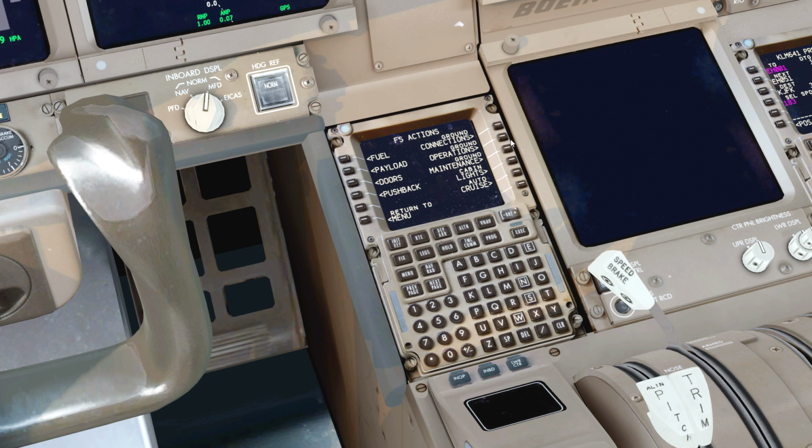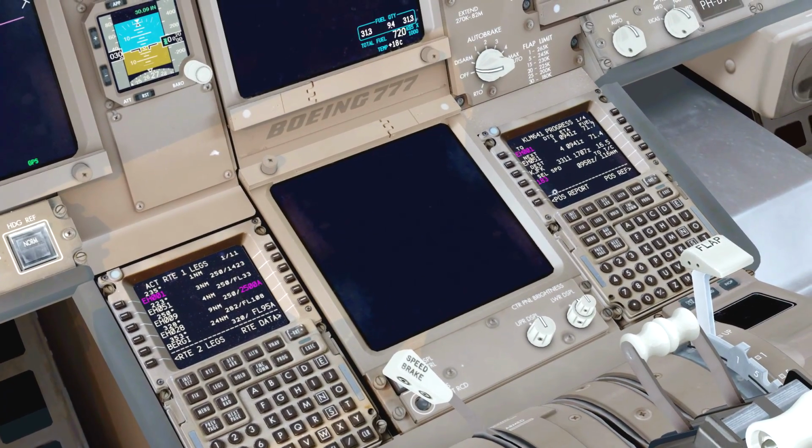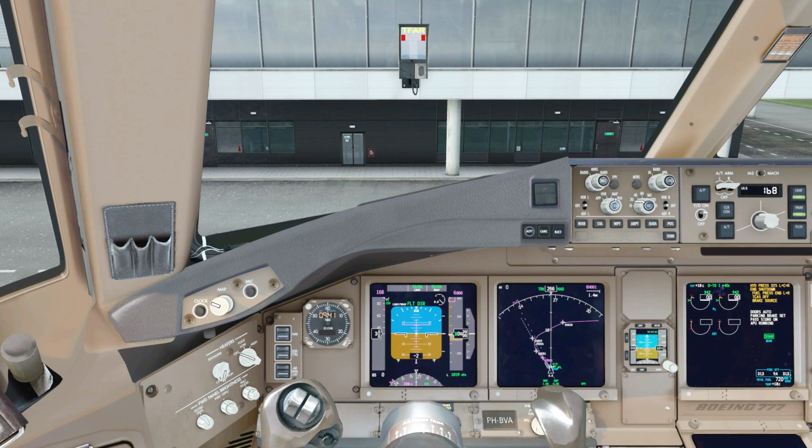And in order for the ground crew to further set up the pushback truck, we're also going to remove the wheel chocks like this. Okay, so right now the pushback truck will get into position and insert the so-called bypass pin, which makes sure that the hydraulics of the nose gear are disconnected from the aircraft system. And we're just going to open the legs page right here. That's open, and then on this flight management system I usually have the progress page open so I can exactly see how the flight is progressing.